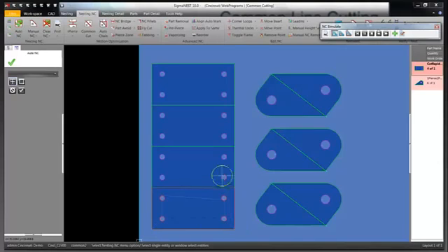Once that part is cut, it is completely free and separate from the rest of them, and this type of common line cutting not only decreases cut time, it actually increases part quality versus other styles of common line cutting because you are able to remove it. We do have options as well on cutting all the holes first and then coming back and doing the common line cutting.